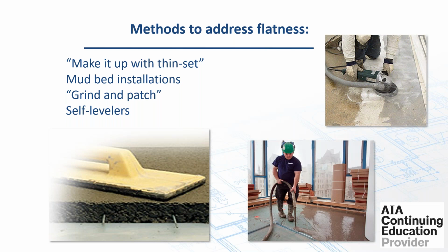Mud bed installation is another way that we address flatness in the tile industry. Patching and grinding: sometimes if it's sporadic irregularity in the slab, you can grind down the high spots and just patch up bird baths. Or for that matter, self-leveling. Self-leveling has really grown for the tile industry. It's been around forever for the other flooring industries, but for the tile industry, it's grown enough that we just recently added ANSI standards to the Tile Council, to the ANSI handbook, for self-levelers. I'll get into that in a little bit more detail.